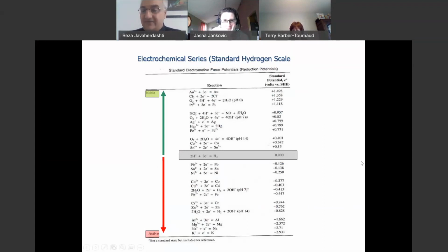That's why, in addition to the electrochemical series, we have two more hidden weapons to let us determine anode and cathode. The other one is the so-called galvanic series. The galvanic series basically ranks materials based on the environment and a standard temperature. You construct a galvanic series for, say, 25 degrees centigrade, only for seawater. Then you say that if the environment is seawater and the temperature is 25 degrees centigrade, then this metal will become anodic with respect to that metal.